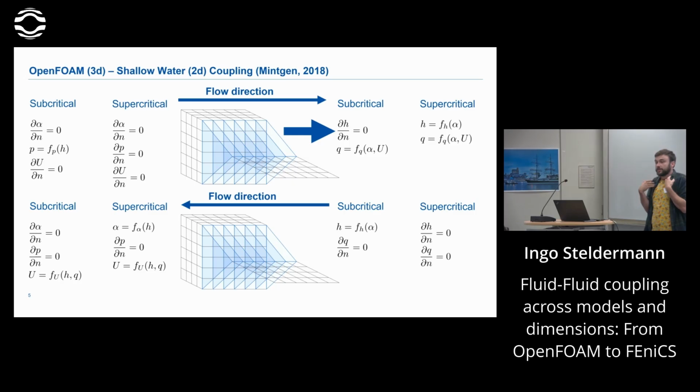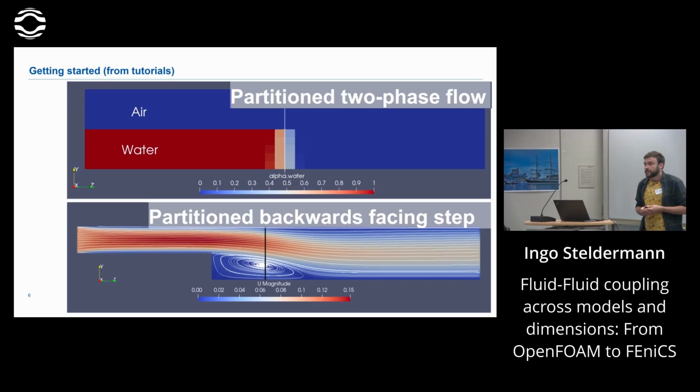So at this state of my project, starting with coupling, I'm like, let's just reproduce what he has already done and try to find a way to build this in OpenFOAM. And this boundary condition is essentially a 0 Neumann boundary condition for the water height on my shallow water flow solver. And a second one, that's why I introduced this notation of f of q, here we want to impose a Dirichlet condition on my discharge, so the water height multiplied by fluid velocity, built on the information from the other side, right? So this is where information comes in from OpenFOAM, and I need to convert this. I need to go down this triangle here, reduce my data to this single point.